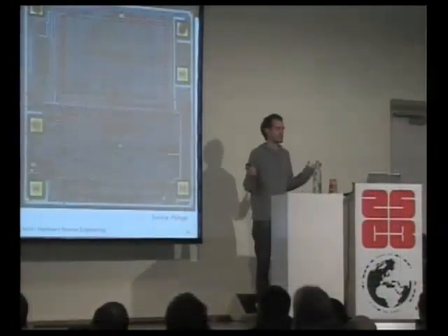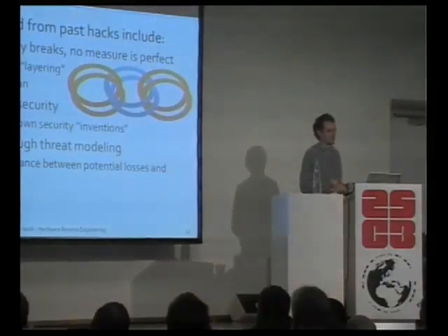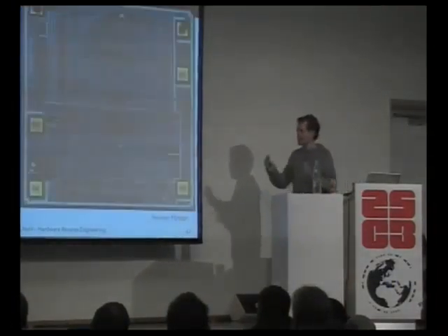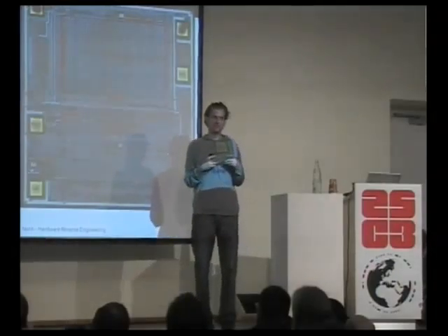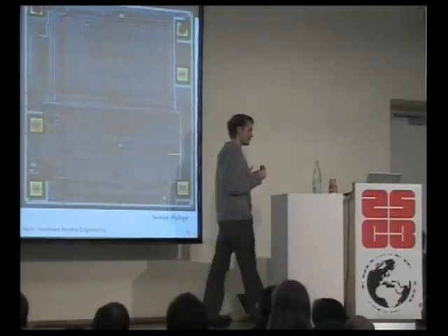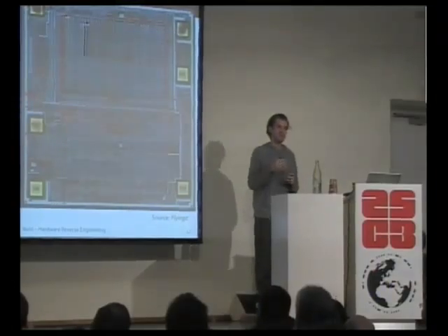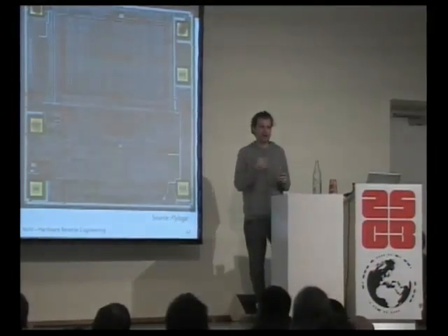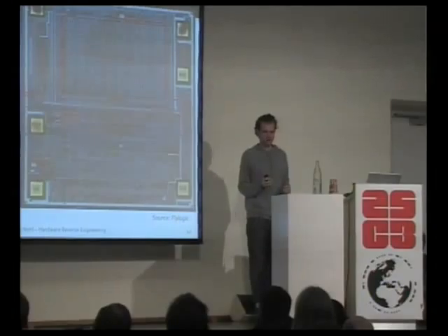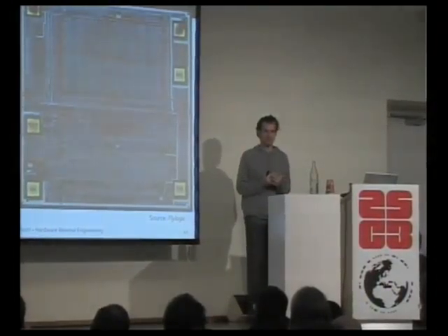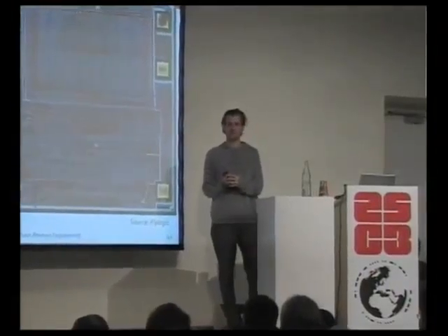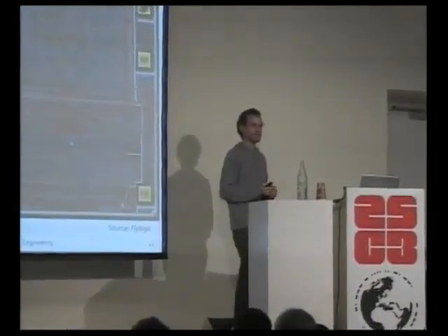So really there is no good solution for secret key storage. And I don't know how to build this solution. What I'm trying to get across, though, is that if you are building hardware and you are already using good cryptography, do not rely on the fact that your keys are securely stored. Try to store them in as few places as possible and prepare for the case where your master key gets compromised. Have good key rollover schemes.